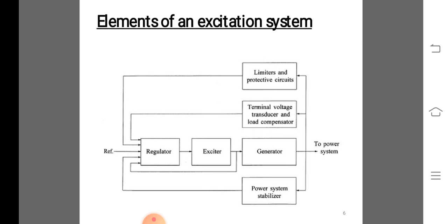Then the brushless excitation system. An alternator with rotating armature and stationary field is employed as the main exciter. Direct voltage for the generator excitation is obtained by rectification through a rotating semiconductor diode network, which is mounted on the generator shaft itself. Thus, the exciter armature, the diode network and the generator field are rigidly connected in series.